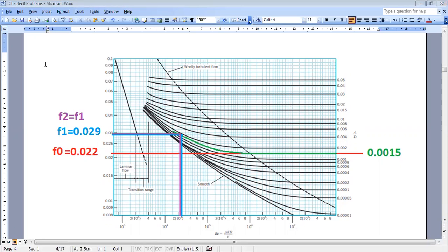You have rho, the density of the fluid, because whenever we have a fluid in general, the most important characteristics are rho, mu, and velocity. So these are important characteristics. Plus here, since we have roughness of the pipe, so here my pipes are rough.